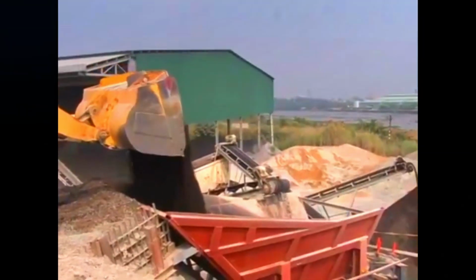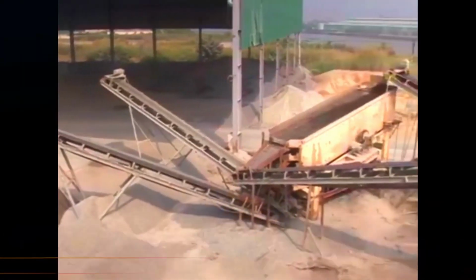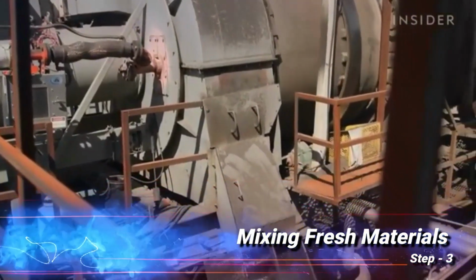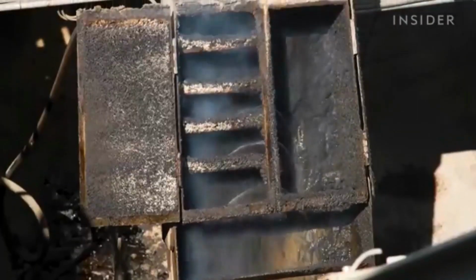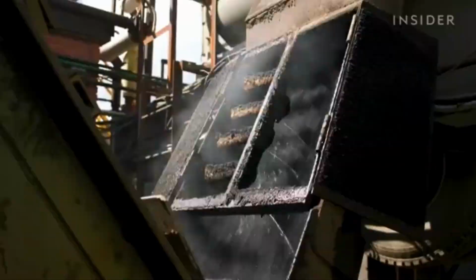Step 2. Crushing and screening. The reclaimed asphalt is crushed into smaller particles and screened for size consistency. Step 3. Mixing with fresh materials. The recycled asphalt is heated and blended with new bitumen, rejuvenators, and aggregates to enhance performance.